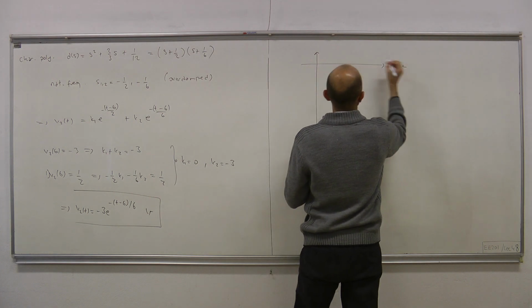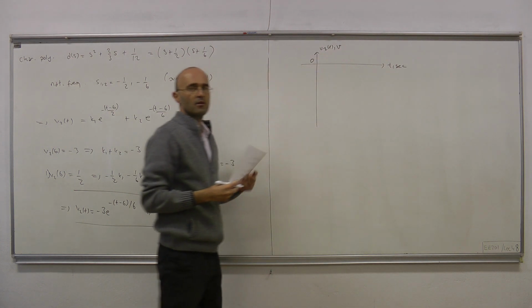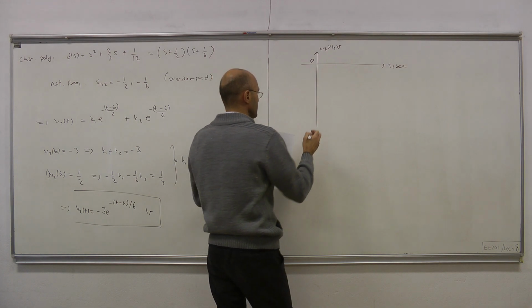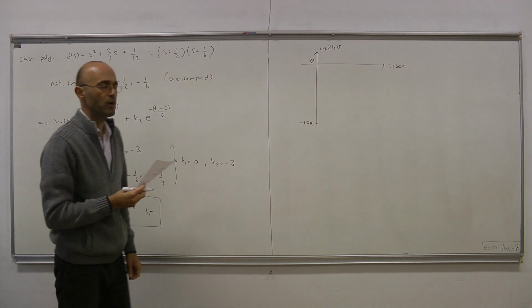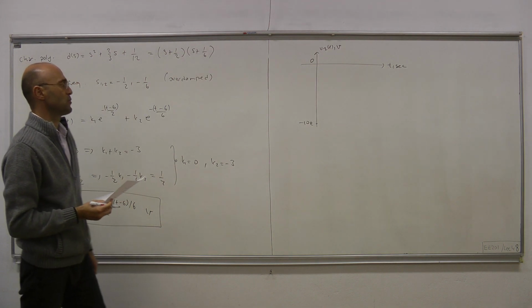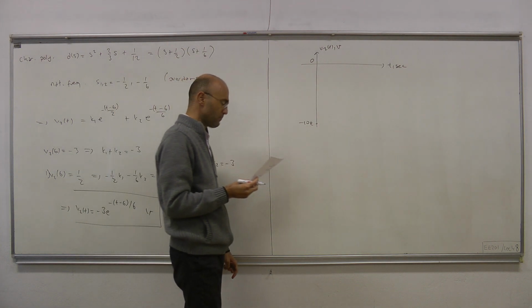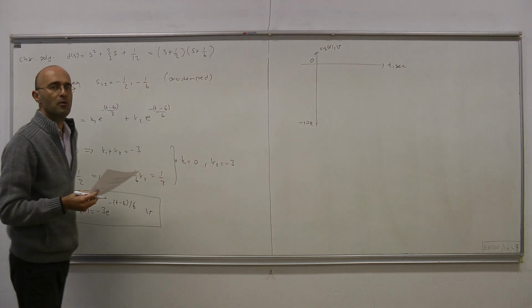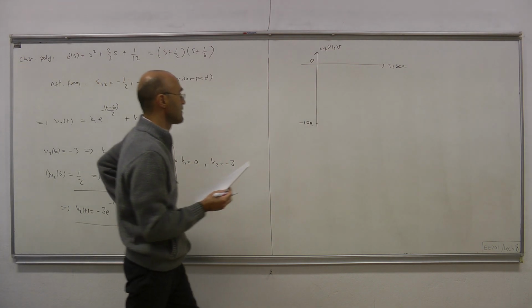Okay, t in seconds, V2(t) in volts. So initially we read minus 10e, so that's given. We're somewhere here, minus 10e. e is 2.71828, so it's about minus 27. And until t equals 6, what's happening is we're decaying towards 0 with a time constant of 6.